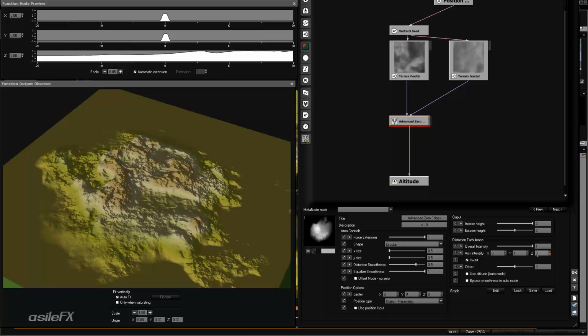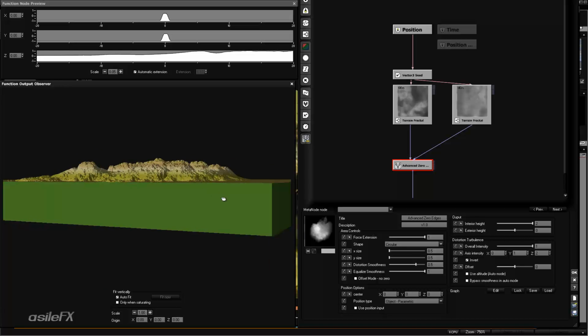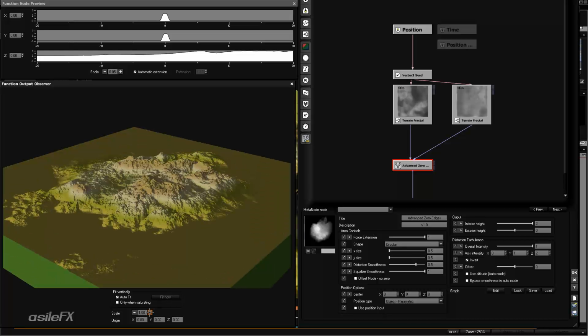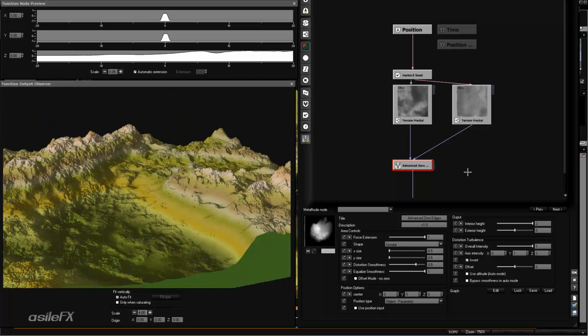Set that to 0, and we're going to see no change, regardless of the input that's being used. We'll go back to the other position input, because like I said, it does end up being faster for the renders. If we do notice any artifacts or problems, cracking or breaking of the terrain, especially around the really rocky areas within terrain fractals, I've noticed you can have some holes that show up within the terrain, and that's because the geometry amount is really being reduced, and the roughness value is removed.